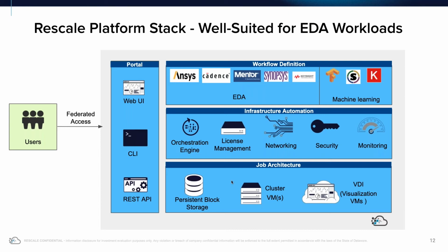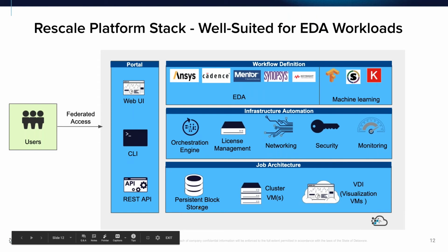When we are running these workloads, an important piece is, hey, how do you manage my process design kits, right? How do I host them? We have developed features specifically addressing this challenge. We have persistent block storage, running an NFS filer system, so you can spin up a shared node, put all your PDKs in, and then create your simulation environment so that you are able to run any type of workload, whether it's LVS, DRC or SPICE simulation. That part is handled through our persistent block storage.